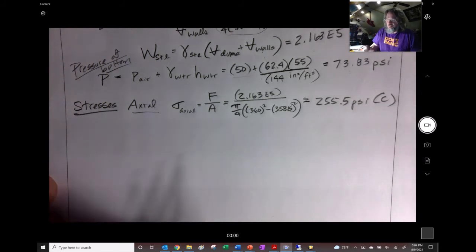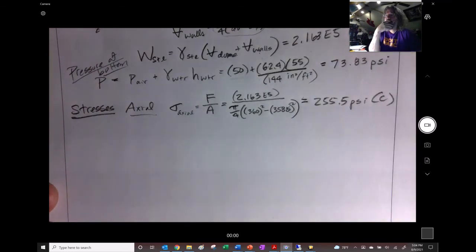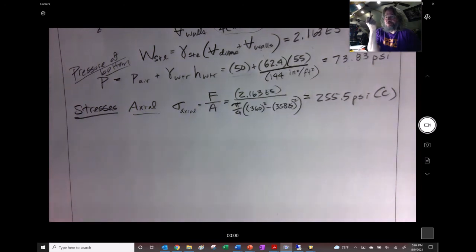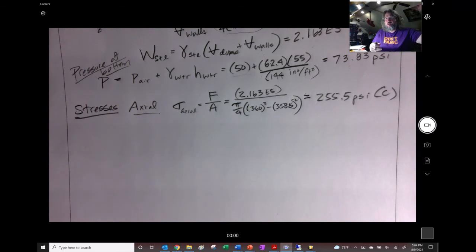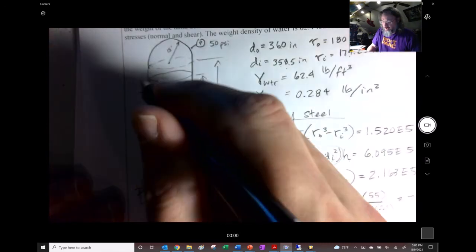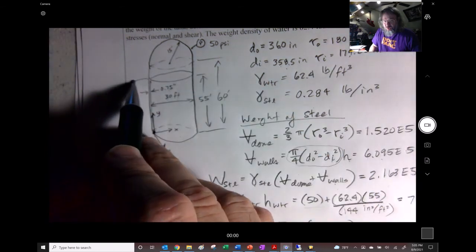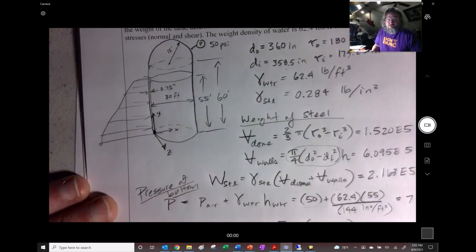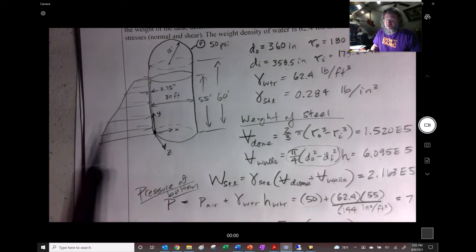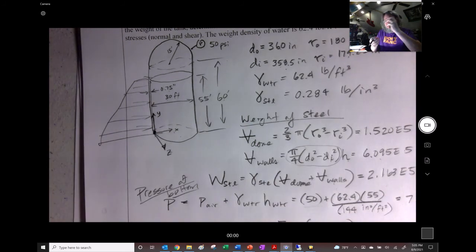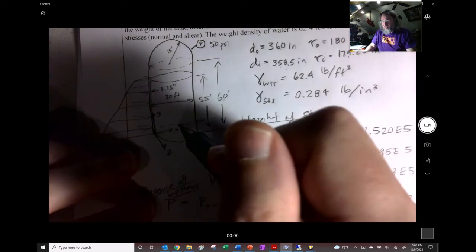You want to make sure that you're a thinking engineer. So you start to pick apart and say, okay, what is longitudinal stress? Well, longitudinal stress is really the thing that's holding the thing from flying off into space, right? Well, when it comes to our scenario right here, although the pressure, and we could even draw it like a pressure gradient, right? We could say it starts off with a pressure here and then the pressure gets larger, right? So if there's a pressure gradient that we were drawing onto the thing, it would be distributed like that right there. And pressure acts in every direction, but when it's the hydrostatic, we're picking the thing up. It's getting less and less.